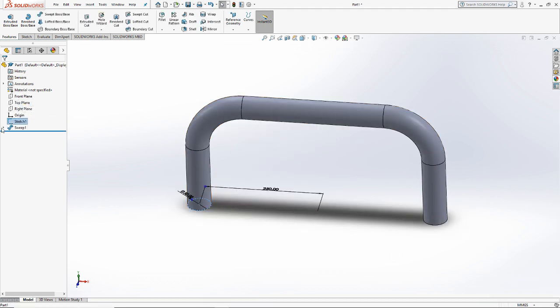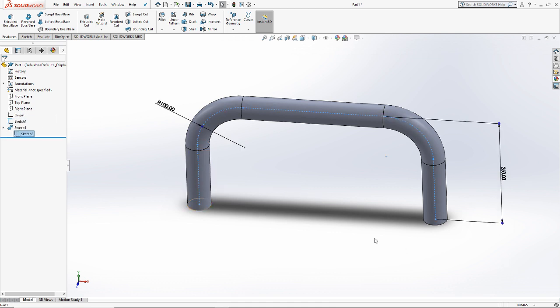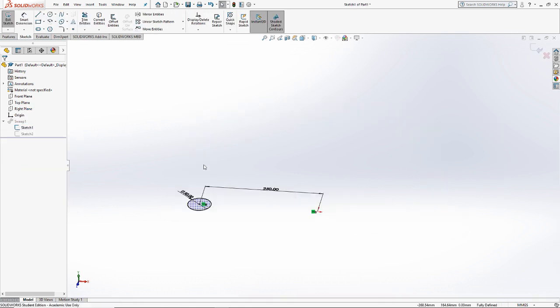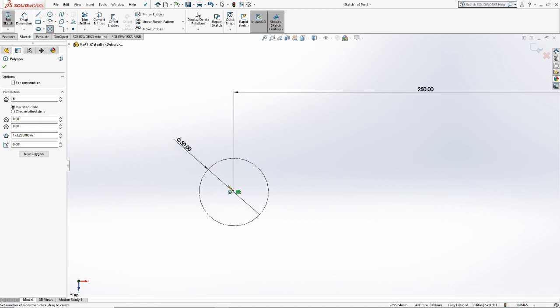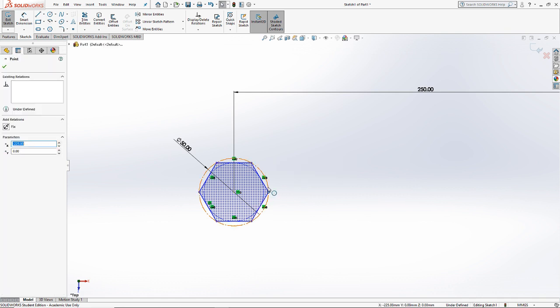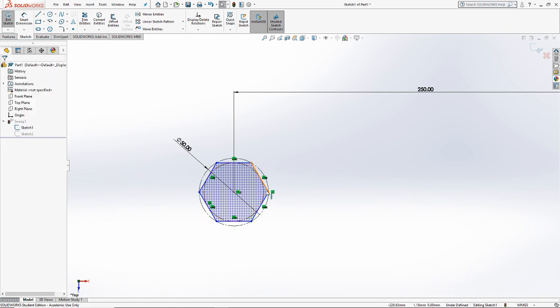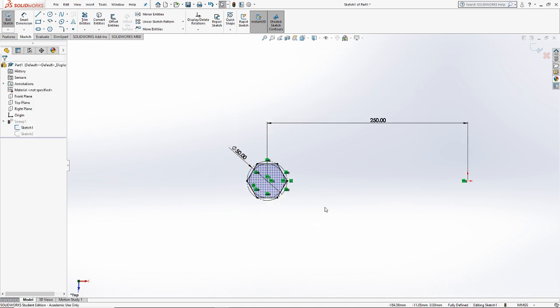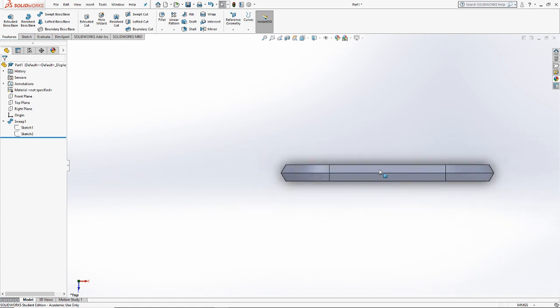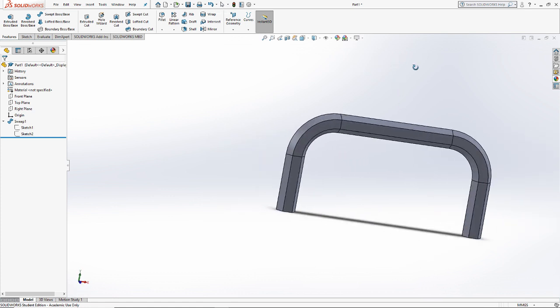Apparently, when I delete that sketch, because I referenced it in the other sketch as the endpoint of the line, it disappears. But for example, I could use that sketch to define more interesting geometry if I wanted to. Like if I switch this circle to a construction line, and I switch to, I don't know, like a hexagon or something. Nothing cooler than hexagons, that's my motto. So I'm going to tell SolidWorks that the edge of one of the nodes in the hexagon should be horizontally aligned with the origin for no reason in particular. Now look at that. That's a much cooler handle, right?